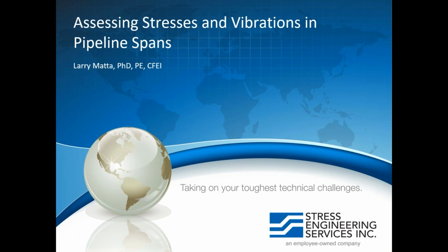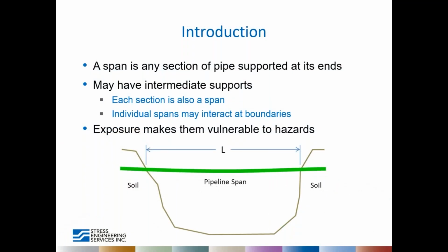prefer not to fly. Here at Stress, my pipeline work deals mostly with unusual loads on pipes like the spans we're going to talk about today, vibration issues due to things like compressor pulsations, water hammer and surge, surface loads, the effects of blasting on pipelines, and some other unusual things. But today we're here to talk about risks to pipeline spans, which come primarily through steady state stresses and vibration issues. And so let me start with a definition of a span.